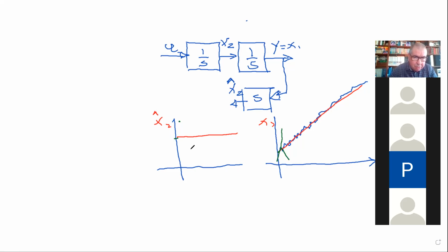It's probably even a negative value, and then it's positive again. So you start having something like this. You see? So you are amplifying the noise. So the derivative has these two problems. It's non-causal. And if you have noise, even a small amount of noise, you are amplifying the noise in your estimate. You agree? Yes. Okay, so I can clean up this. My sketch was very bad, but you understood the point.